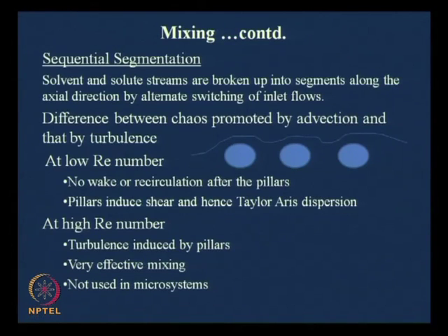However, at high Reynolds number, you can expect turbulence induced by pillars. That is very effective mixing, because there you are creating cross eddies, and that helps in the mixing. That is why you put these pillars wherever you need mixing, in heat exchangers, in membrane separation units. However, this is not used in microsystems, because the Reynolds number is not in that range. All right.